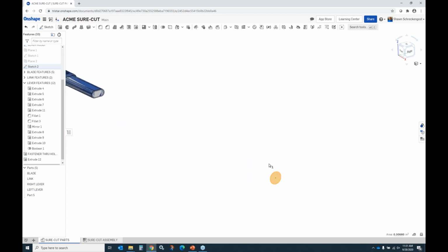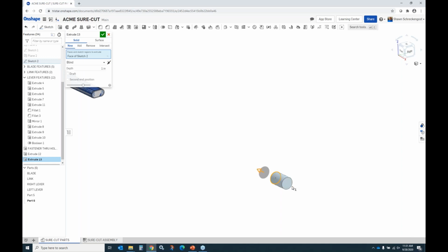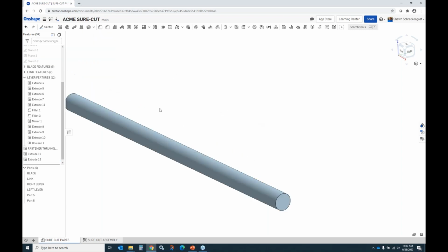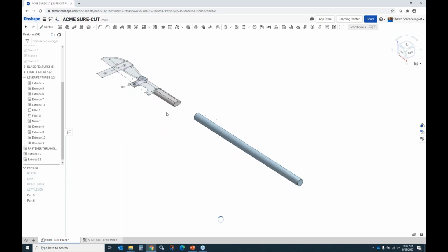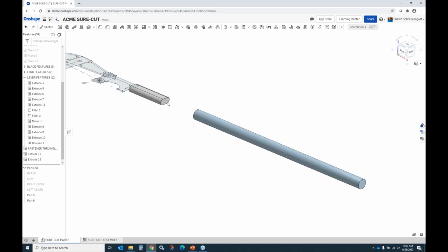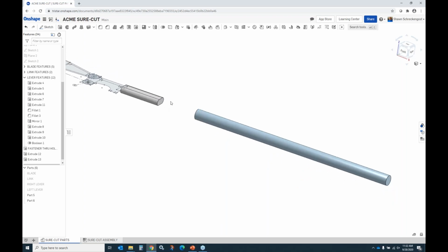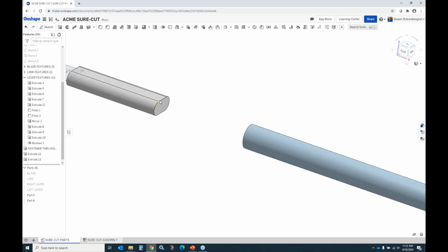I'll go ahead and extrude this sketch as well, in the other direction. And this one I'm going to extrude about 13 inches. Since it doesn't touch any other part, it'll automatically be created as a new part. Okay. Now I'm going to isolate just those 2 features, and join them together with a loft because I want to transition from this oval shape to this circular tube.